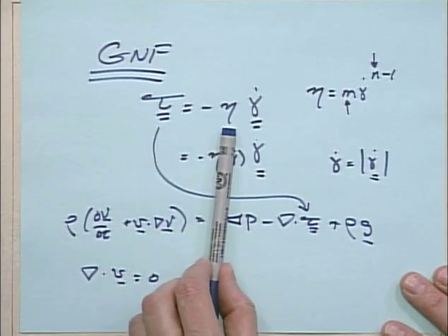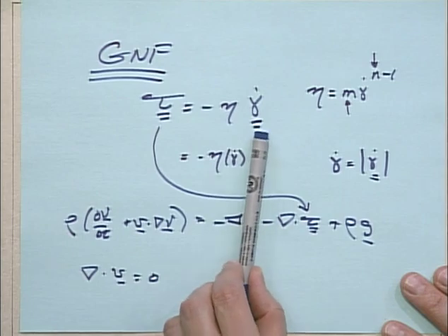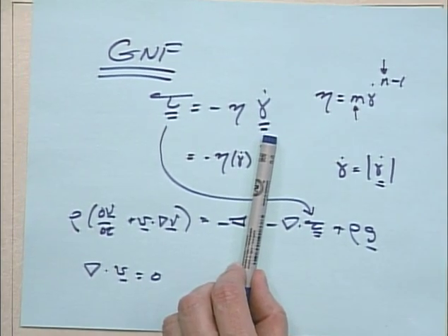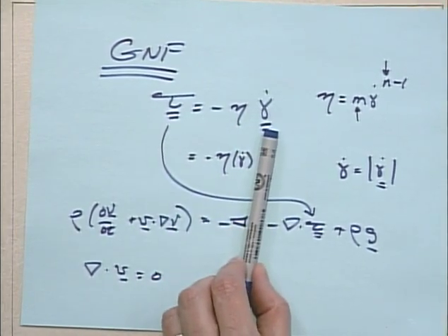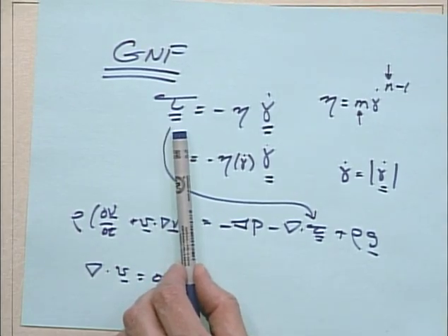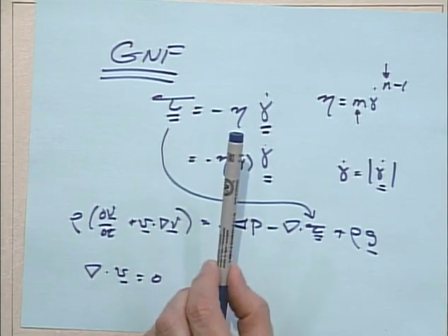This is a function of the magnitude of the tensor, and this is the rate at time t. So if the rate is 0, like in this plot at time less than 0, the stress is 0. If the rate is something, the stress is that something. And so here in the startup experiment, when it steps up to a constant, that means that the stress is going to step up to a constant also.